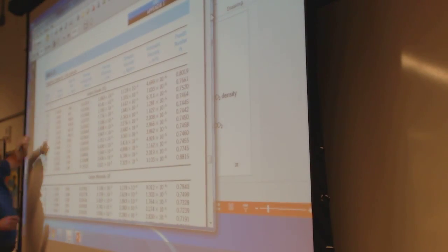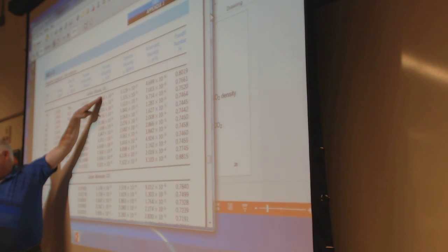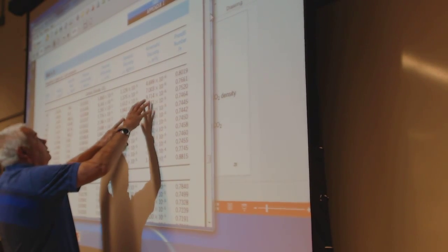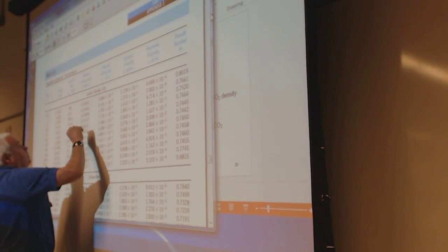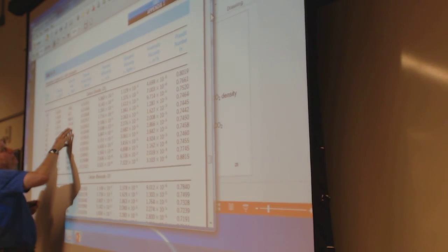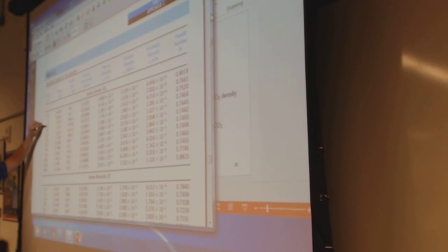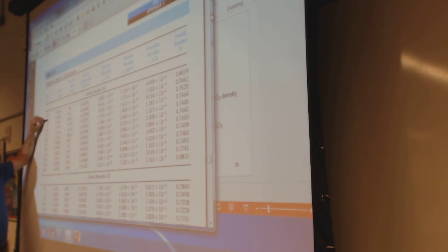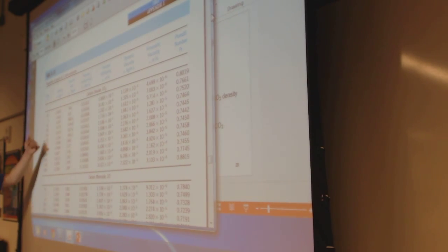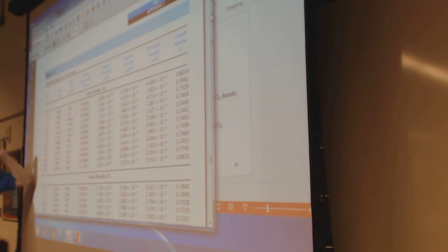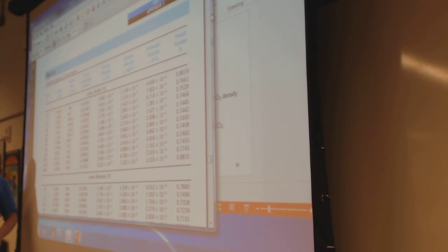And so here are properties of gases, and carbon dioxide is one of the gases. We've got a bunch of different properties. This is used in heat transfer, this is used in fluids, the viscosity, that's basically heat transfer. Here's the thermodynamics kind of properties. I want a value at 25 degrees C. I have 0 and 50. Oh boy. And you notice there's a difference there. We're halfway in between. I'm going to have to interpolate.